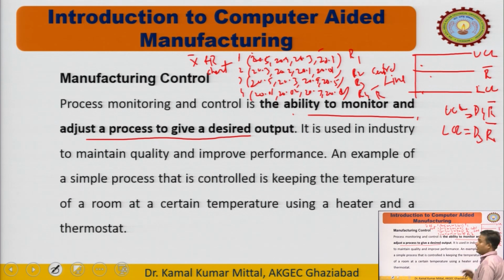So these are the upper control limits and lower control limits. These we can calculate, and these D3, D4 depend upon the sample size. So in this case 4 samples are there, so D3, D4 is different. We can take the values from the statistical table. If sample size is 3, 5, so these values differ. उनकी वैल्यू अलग अलग होगी यदि सैम्पल साइज अलग अलग होगा.